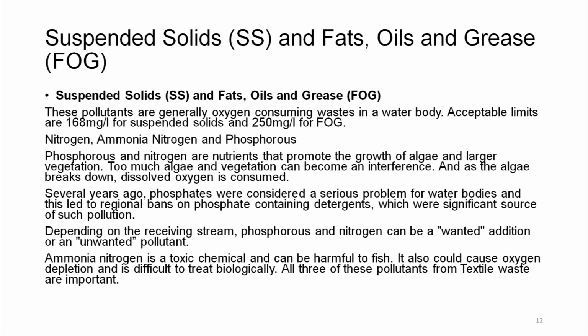So, ammoniacal nitrogen is a toxic chemical and can be harmful to fish. It also could cause oxygen depletion and is difficult to treat biologically. All three of these pollutants from the textile wastewater point of view are very important. So, we cannot ignore nitrogen or ammoniacal nitrogen or phosphorus, because all of them put together have an adverse effect or have an adverse load on the textile effluent.